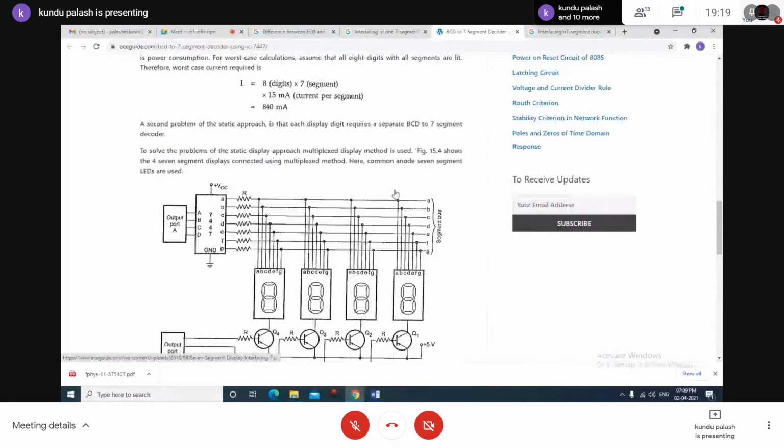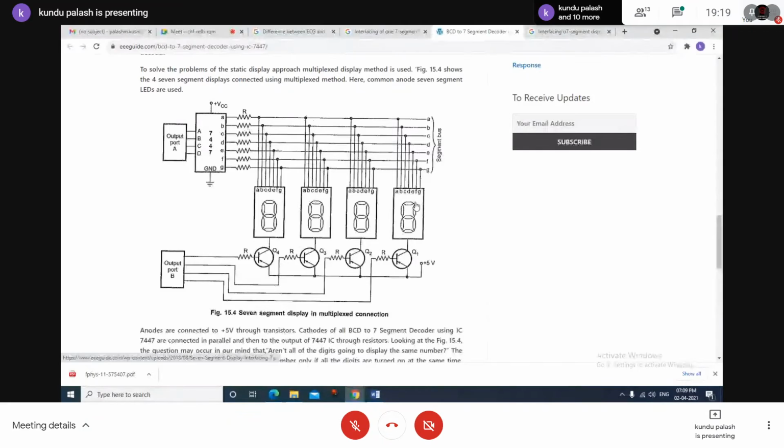Here we see the 4 digits, each digit is a 7-segment display, and there is a digit drive signal which is connected to the 4 driver transistors. So what type of 7-segment display is to be used, we can see from the logic diagram. When the digit signal is high logic, the transistor will get the base bias signal from the output port, that means when this port line becomes low, the transistor will conduct, and the common line must be anode. So each 7-segment digit follows the common anode type logic.